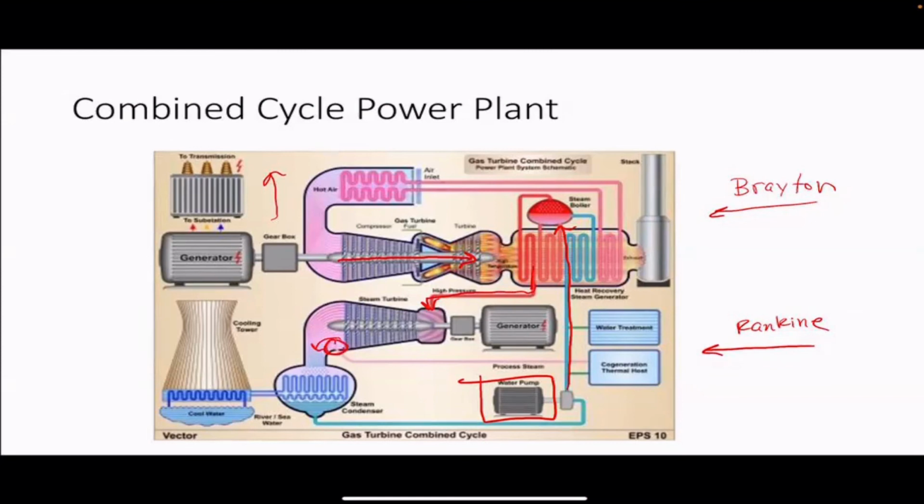So you actually could input a cogeneration line here if you wanted to, just like we showed on the previous slide, and then send it to the condenser, then back to the pump, and just run this continuously. And if you do this, it's actually not uncommon to have combined cycles that can get efficiencies north of 45%, where you convert the thermal efficiency into electricity through the two generators.